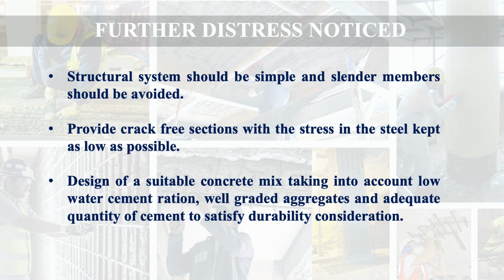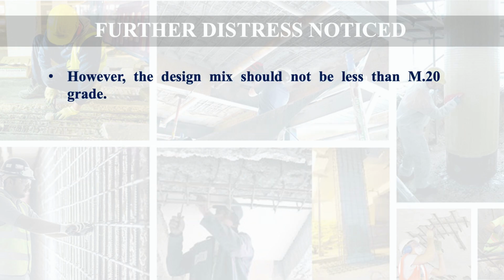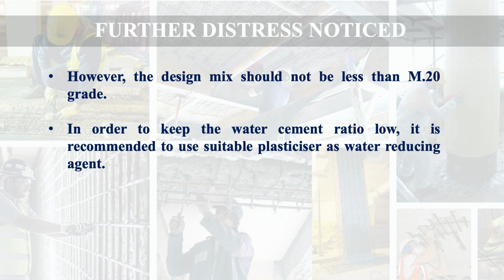Then design of a suitable concrete mix taking into account low water cement ratio, well graded aggregates and adequate quantity of cement to satisfy durability considerations. However, the design mix should not be less than M20 grade. In order to keep the water cement ratio low, it was recommended to use suitable plasticizer as water reducing agent.